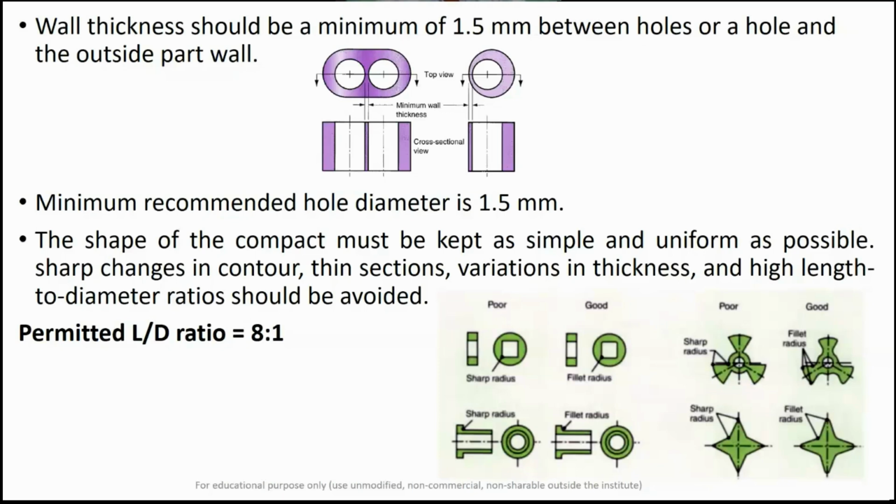After that, you can also observe some buckling in the part after the sintering process. So such mistakes should not be made while designing the part. In this case, for a feature like this, suppose you have a slot or a hole, this sharp radius should not be formed in the die; rather, you can make a fillet radius in the sharp corner. Similarly, if you have a stepped radius, there should not be a sharp radius in your part, and you can make it into a fillet radius.